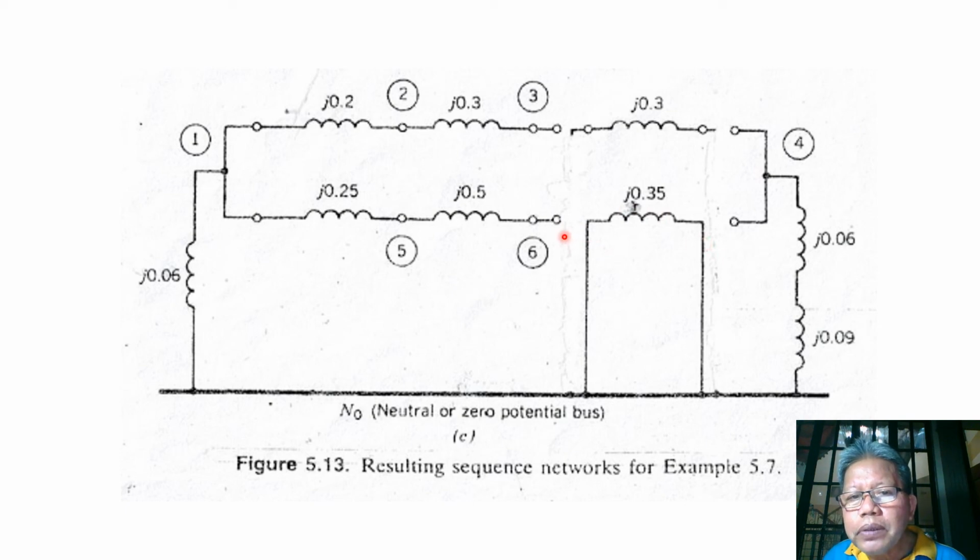For the primary winding, it is open, and at the secondary winding, it is open. And because we have delta at the primary and delta at the secondary, the zero sequence current will just circulate, no? So we represent our circuit as this, meaning circulating currents may be flowing here. It cannot go out to the primary or to the secondary terminals.